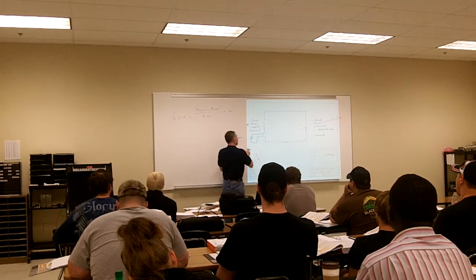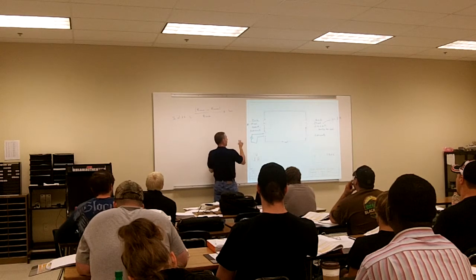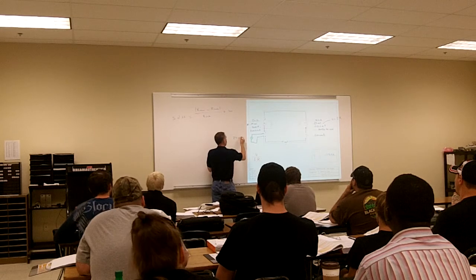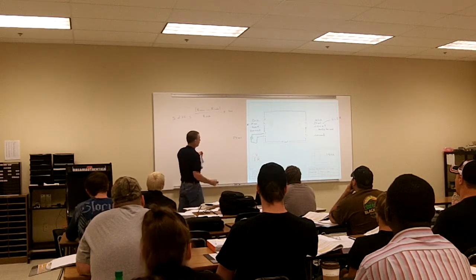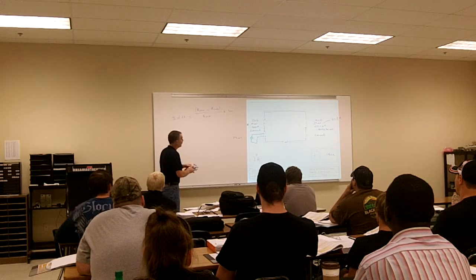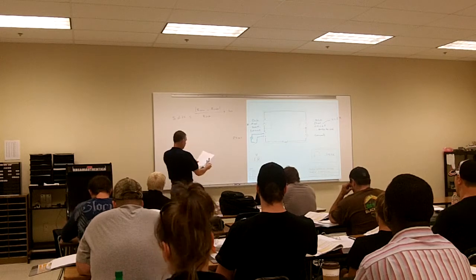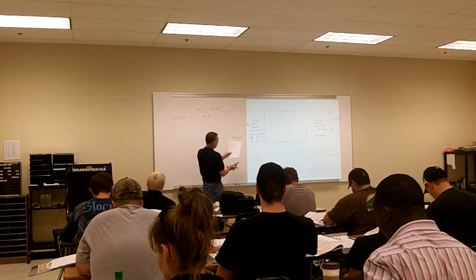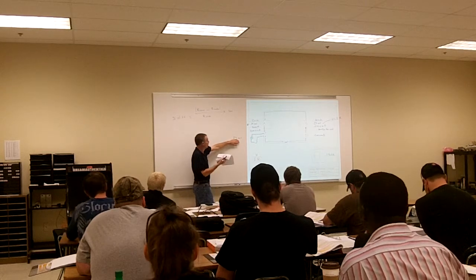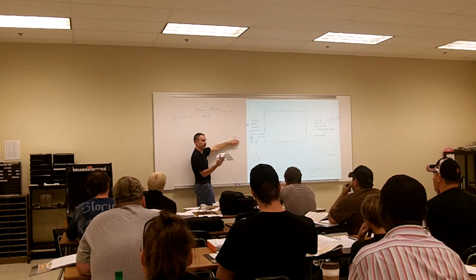Let's go back and let's look at it the other way then. Let's say I ended up measuring 24 volts across that fuse. Is that fuse good or bad? Okay, so let's take a look at it. I got to give you a little hint here. So measuring voltage across an open, so I'm measuring voltage, right? So is that fuse an open or a short?